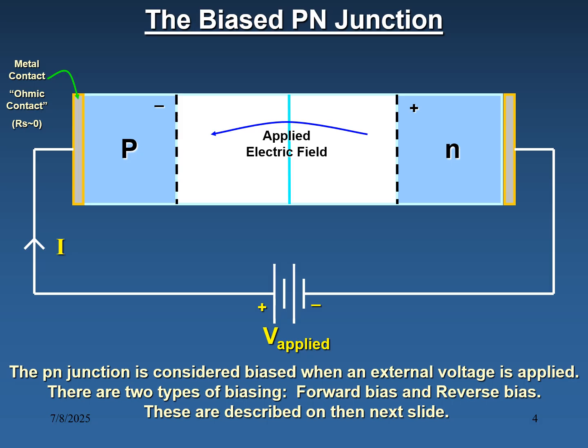That means the depletion width decreases. The lack of charge carriers here, the depletion, is filled by the holes, and here it is filled by the electrons. So whenever the applied voltage increases, the width of the depletion layer decreases. At a certain point, the width of the depletion layer becomes 0. Then there is a flow of the charge carriers from P to N and N to P.